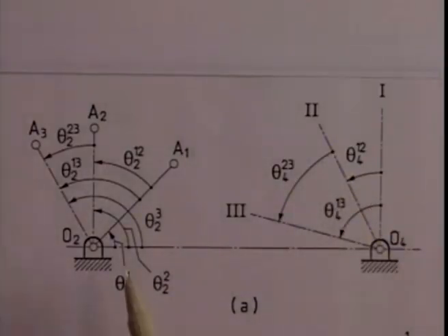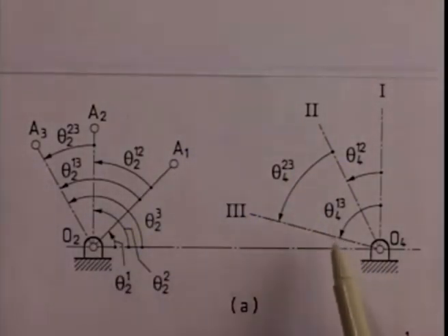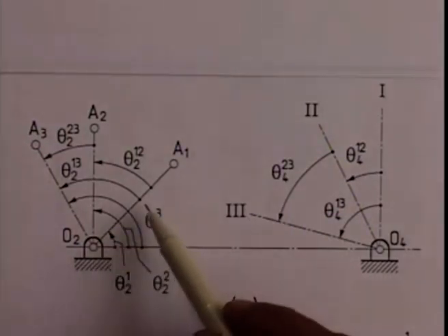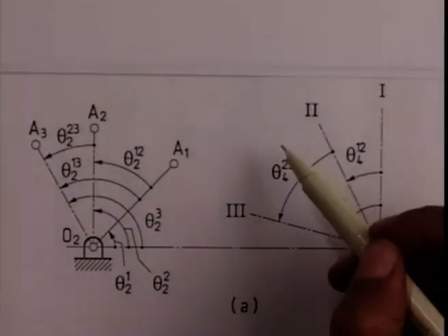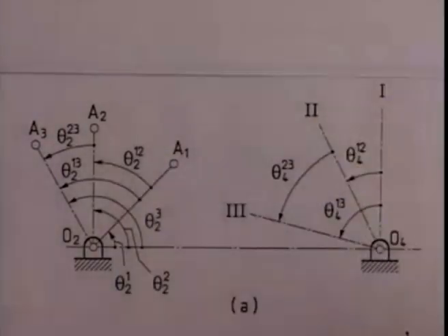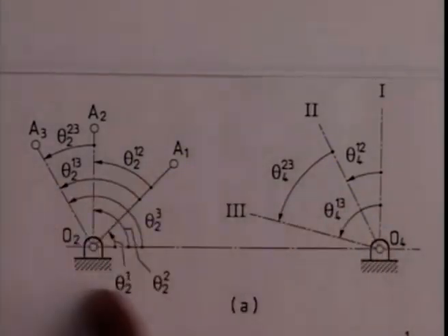We proceed as follows. We assume the locations of O2 and O4, the fixed pivots, according to our convenience. We also choose the crank pin A1 arbitrarily. The only thing remaining is to determine the location of B1, the other moving hinge, such that O2, A, B, O4, the 4R linkage, is completed. To do this again, we apply the principle of kinematic inversion. If we want to locate the point B1, then we should hold link 4, that is the follower link, fixed at its first configuration and allow this fixed link O2, O4 to move such that the same relative movements are maintained.